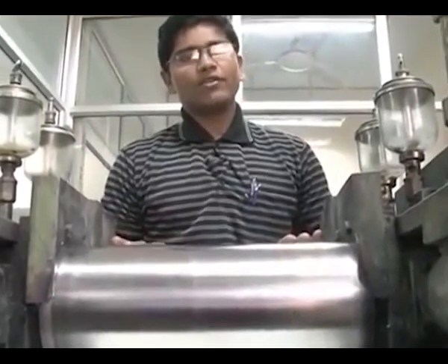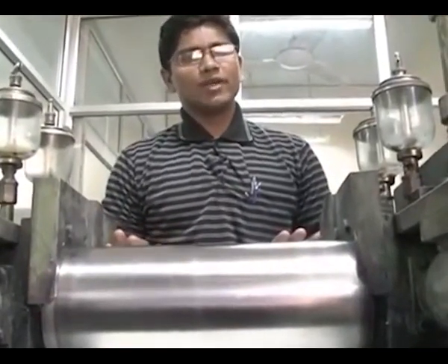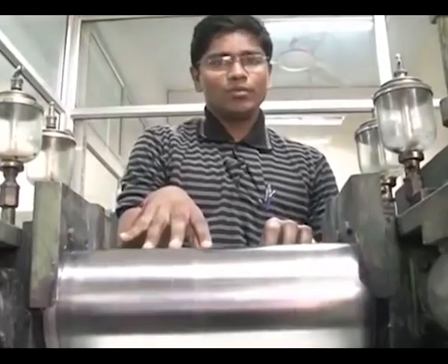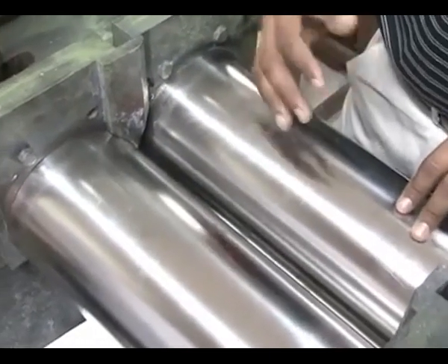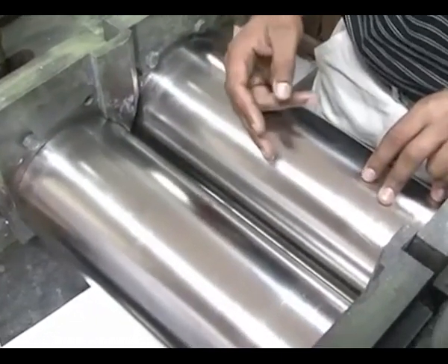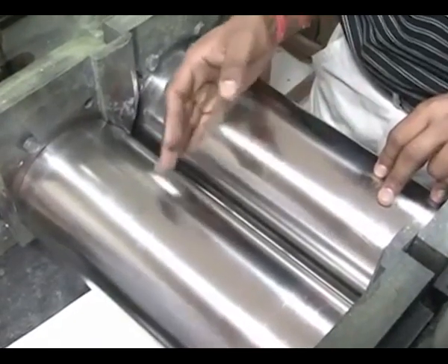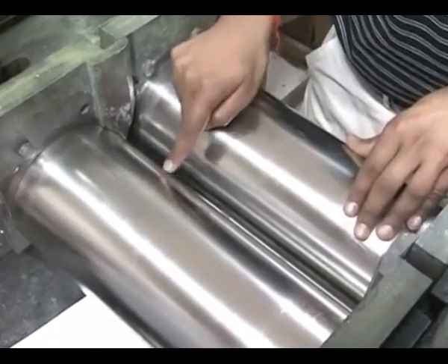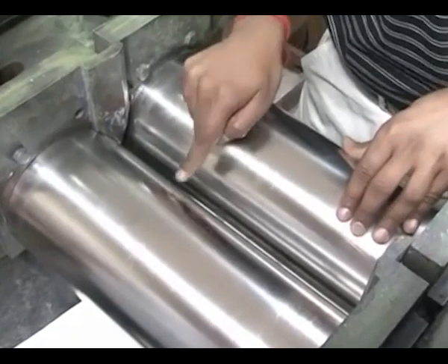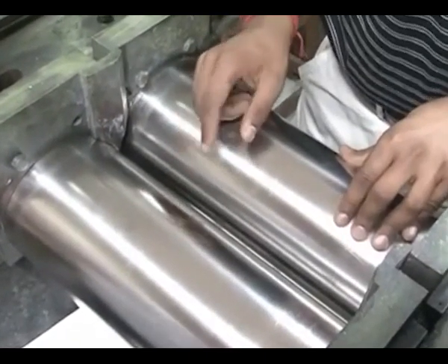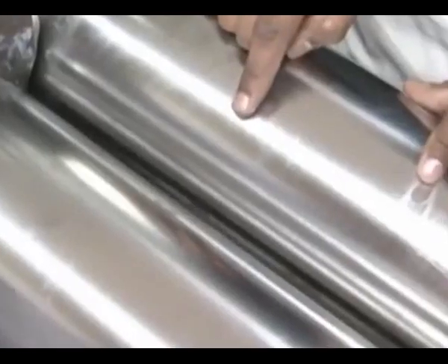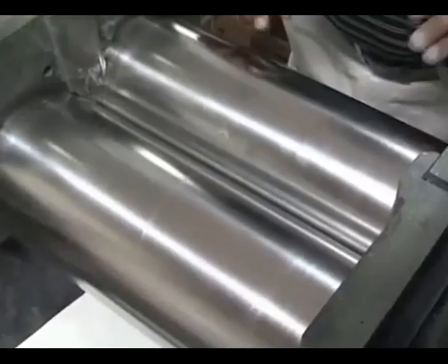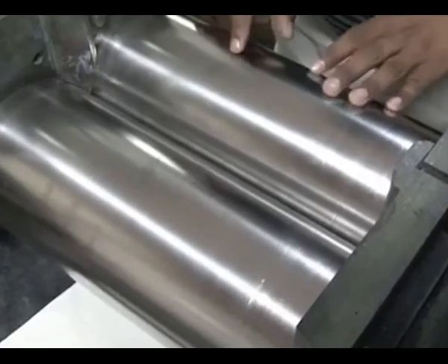This is the two-roll mill where we fabricate the polymer rheological abrasive medium by mixing with two rolls. In this, one roller is the supporting roller and one roller is the grabbing roller. Once you are processing the medium, the medium will stick to one roll and the other roll supports in rolling. The gap between two rolls is called the nip, and this is variable. You can vary the gap. Now you can see the variation in the gap. Depending on how much gap you want, you can set the gap. Now you can see the motion of the rollers.